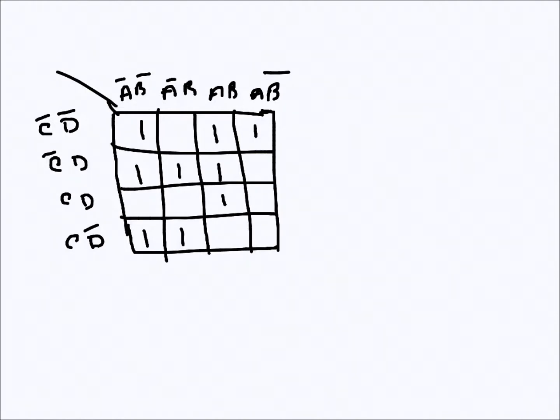From a truth table we get a sum of product expression, which is the combination of AND gates and OR gates. So several AND gates are connected together by the OR gates. So that expression can be minimized using Boolean algebra, and K-map is an alternative to Boolean algebra. To minimize the expression, K-map can be used. So basically